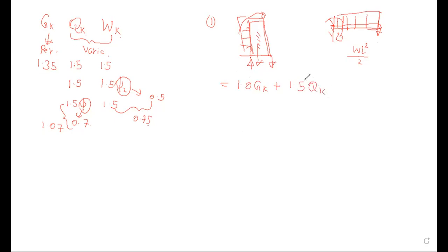We need to see whether there's tension occurring here, because sometimes there will be no tension. So we'll use that adverse load. We reduce the dead load as much as possible. We need to see the maximum, because if we use factored, this tension will be decreased again.